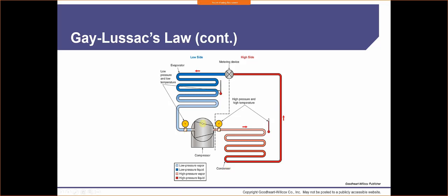The output of that refrigerant now is going to be a high pressure, high temperature gas. We're flowing through outside to the condenser. Once we hit the condenser, we start to release the heat that we've absorbed. As we travel through, we finally get to the point where we're just a hot liquid.